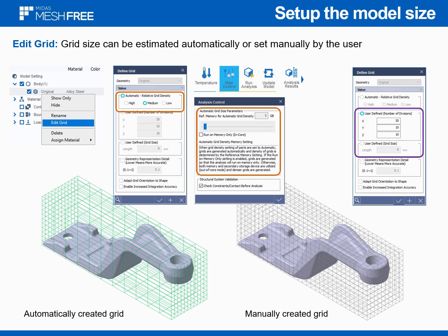So we have to learn how to do this wisely. Not always 5 or 10 gigabytes is enough, or will give you an accurate result. You can get an accurate result using 1 gigabyte or 2 gigabytes, and we will see how to do this. But still, before I go through the next pages, I would like to emphasize that the automatic approach is still the best, and it offers the optimal size of your model, so don't forget about that.